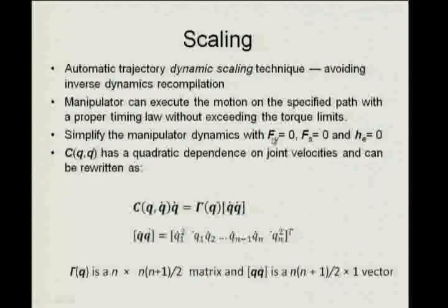Now, we are going to simplify the manipulator dynamics. So I start ignoring friction, drag on the motors, because those are very nebulous things, not so easily manageable. I ignore the end effector forces, because the effect of that is you cannot change right now. So it's too nebulous.